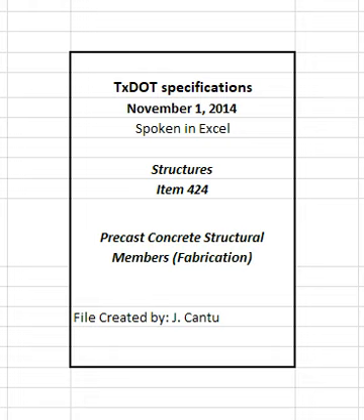Attach each temperature probe to a separate temperature recording device unless multi-channel temperature recording devices are used, in which case one high concrete temperature probe and one low concrete temperature probe may be attached to the same recording device. When accelerated curing is used, one curing enclosure air temperature probe may also be attached to this multi-channel temperature recording device. Inadequate curing facilities or lack of attention to the proper curing of concrete will be cause for the engineer to stop concrete placement until approved curing is provided. Inadequate curing may be cause for rejection of the affected product.